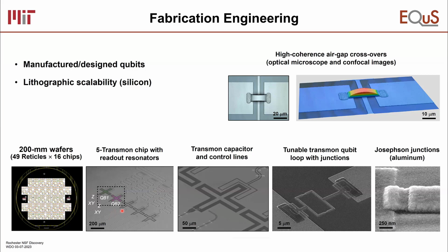So let's zoom in on one of these qubits. You can see this plus sign, capacitance to ground. It's capacitively coupled to a resonator. Turns out it's a lambda over 4 resonator. And then you see one of these control lines coming in and just ending. That's a charge line or voltage line, which we use to do high frequency control. It capacitively couples to this capacitor. And then here we have a flux line, which we use to bias this qubit.